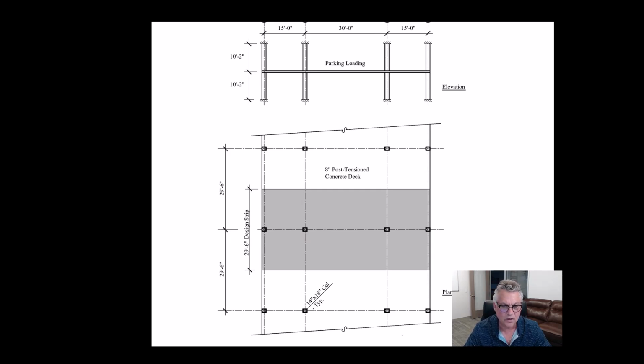And I know I've said all along in this course that secondary shears are relatively small, and it was a code decision not to put them in there. The code is very ambiguous, in my opinion, on how to calculate punching shear stresses.